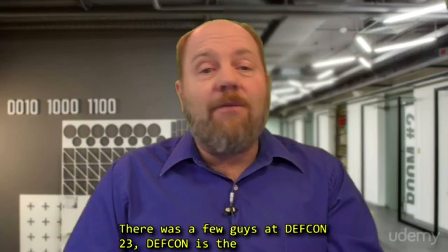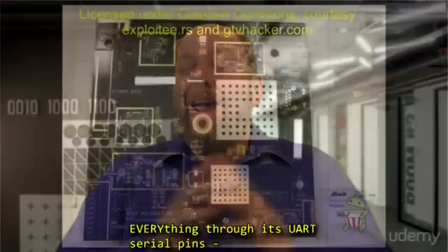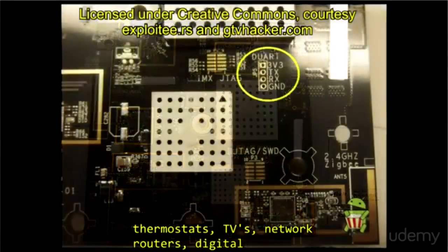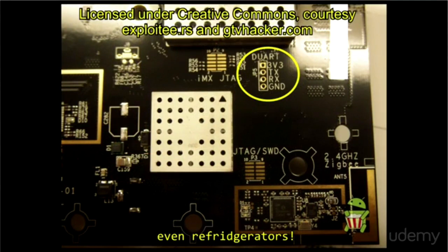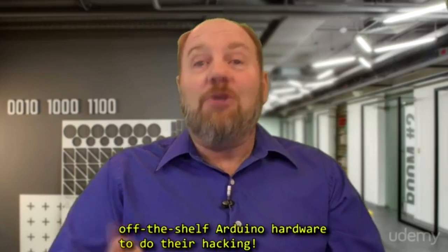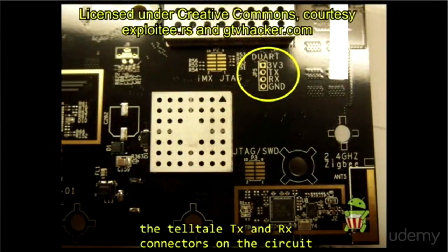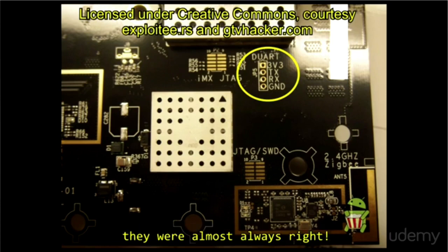There were a few guys at DEF CON 23. DEF CON is the annual hackers convention, and they were hacking everything through its UART serial pins. Thermostats, TVs, network routers, digital cameras, security cameras, baby monitors, even refrigerators. In fact, just to make a point that low-level hackers could do this, they used common, off-the-shelf Arduino hardware to do their hacking. They just cracked open the device and looked for the telltale TX and RX connectors on the circuit board. And they then assumed default UART communication, and they were almost always right.